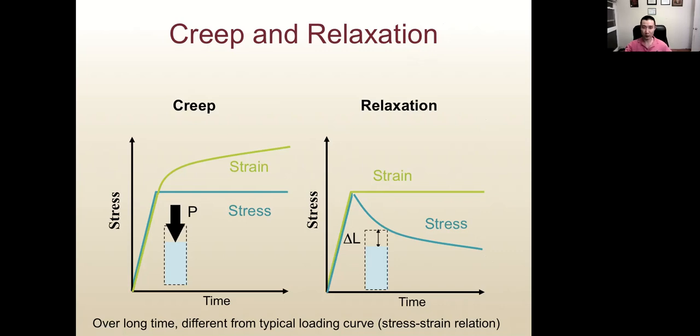Next, let's look at creep and also relaxation. What is creep? If we apply a certain compressive load on a concrete specimen, and we keep the load for a long time, the stress level will not change, but the strain will slowly increase over time. We call this phenomenon creep.